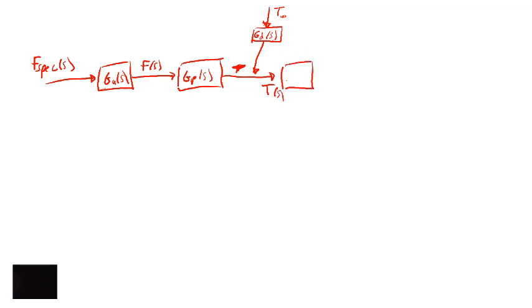In the Laplace domain, this is going to be T naught, and then we might have a sensor. The sensor can have a transfer function, and coming out of here is going to be the sensed temperature. All right, so we can look at this and see that, by knowing these transfer functions, we can essentially determine how this parameter is affected by changes in F specified, or how changes in T naught affect this parameter as well.